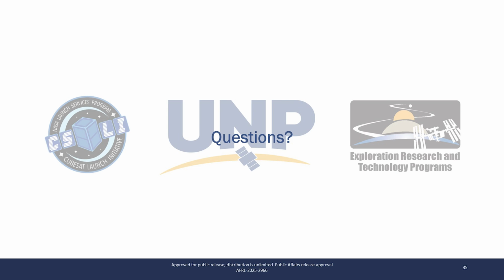But yeah, now all that math becomes linear, it becomes much easier, and we have a lot of tools to manipulate it to essentially minimize the error between those two sets of measurements. And so once you get your best estimate that minimizes the error, you take that and you add that to your current position estimate, and you say, cool, now this is where I am. And then your physics take that value and propagate that forward, and your sensors keep giving you data, and then you do it again and over and over. So you're essentially fusing those two values every time. That's like the top level.